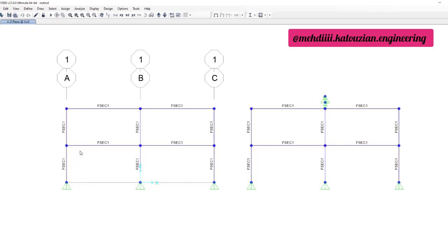The thing which I found I should determine is the total structure weight. The total structure weight is the vertical reaction of a joint. So if you get this reaction, then you can determine about 1% to 10% mass to apply as a TMD structure. When you have the mass of the tuned damper, which I applied in this region, I draw a joint here. I draw a joint, and then with a length, with a length properties.